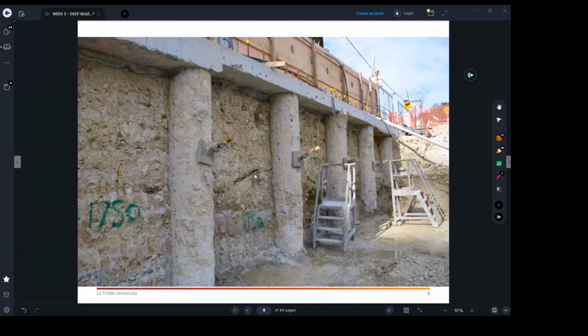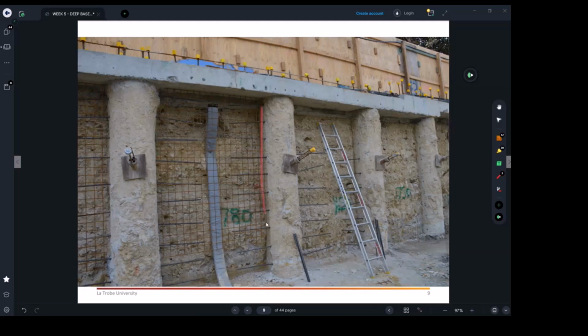So where I was at is, what do we do after we excavate halfway? We have to prepare for the shotcrete wall. What we do, we put this little thing here. We call it a drain sheet. Okay, a drain sheet. What does it do? It will take the hydrostatic pressure. If there is a water table rising up behind the basement, structural engineers typically don't allow for the water to be behind, because it's going to be even more expensive to concrete and design.